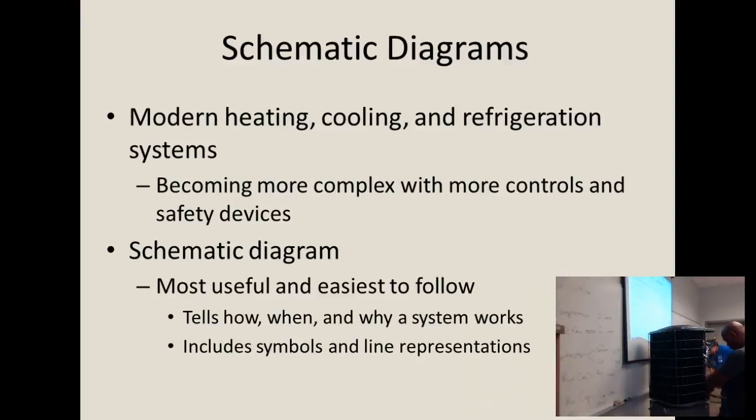Volts, AC. What you said those wires is? 24 volts from the T-stat. And so I'm going to go yellow into the coil, common, which was, one was brown, I think, right? Yellow and blue. Brown and blue. Sorry, blue and brown. No, yellow. No. One on this side, one on this side.